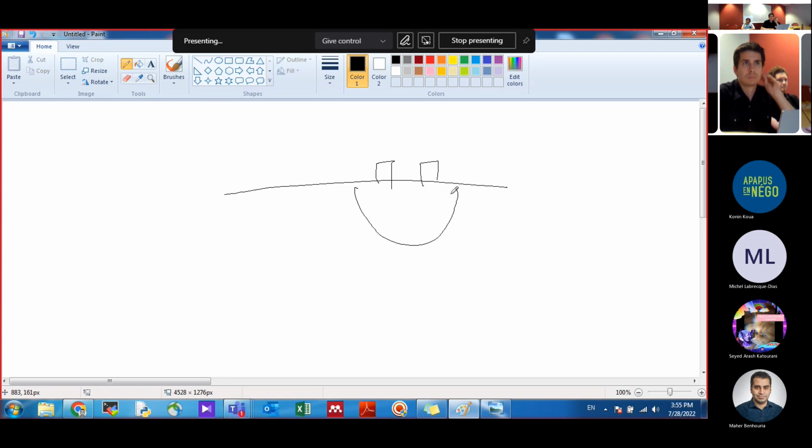Because here that thing is not okay. The implant thing is not okay. So you are going to add dummies and make a distance. Also the same for NMOSes. This one is close to this bad area, this one is not. So you add dummies.